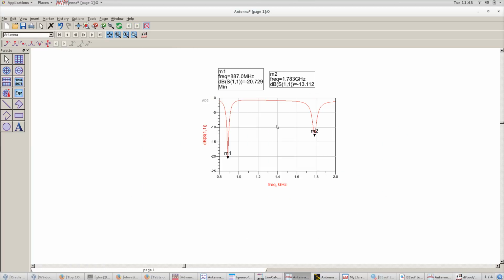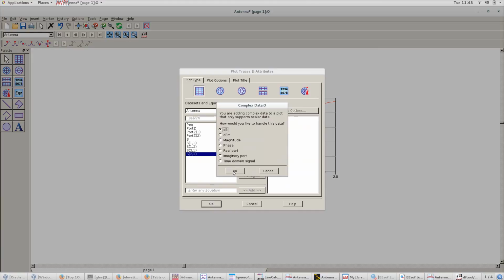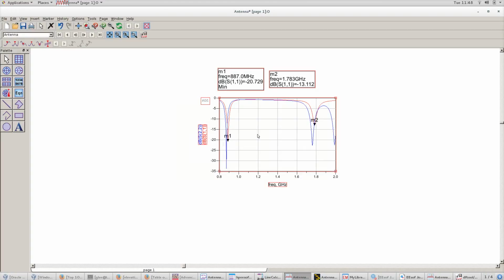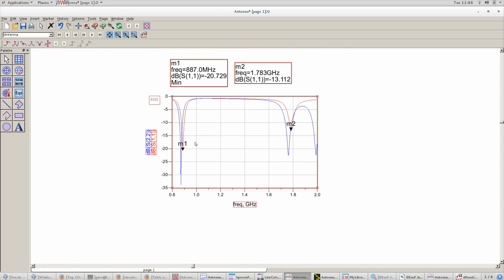Here we go, back to antenna. And see I have S11 on here. I'm also going to add S22. Notice how effectively I shifted over by some amount to the left, actually, from the item. This is pretty common, and this happens a lot when we're doing radiative structures, between our standard circuit simulators and our electromagnetic simulators.